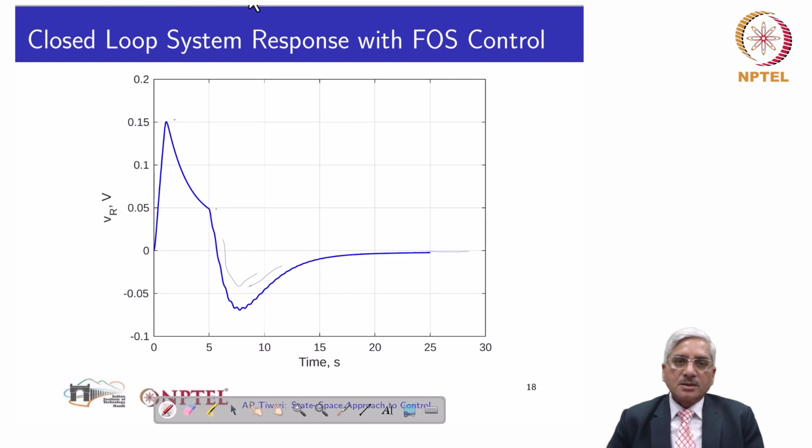An actual reactor system, we should consider the control rod dynamics. We should also consider the internal feedback effects. So a good order of the system will be something like this: 5 plus 1 control rod dynamics, 6 plus 2 feedbacks. So 6 plus 2, 8 order system also one should consider.